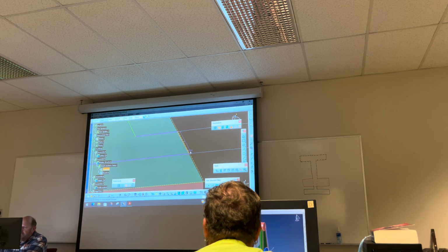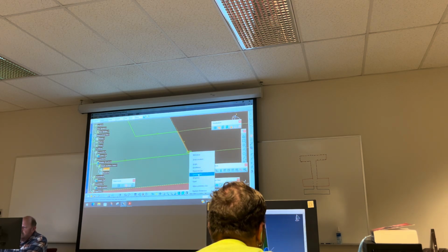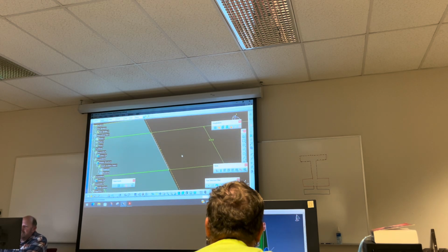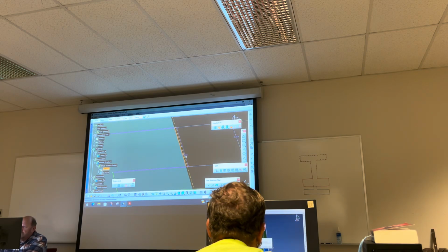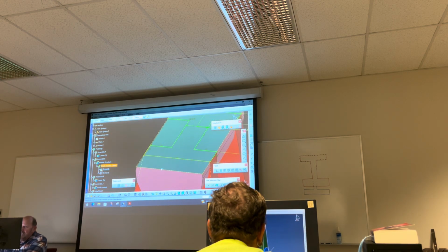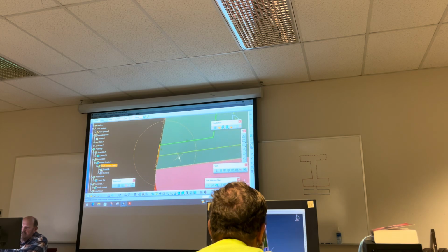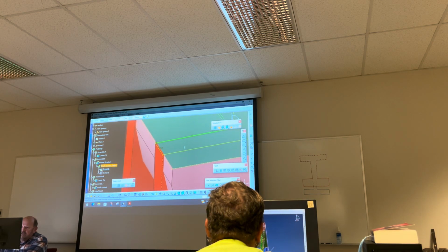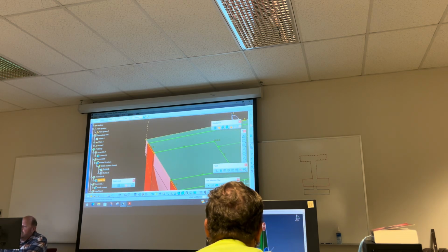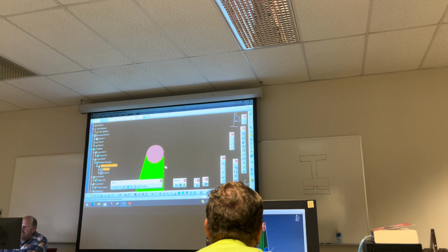So let me pick that, this, coincident. Okay, that moved, and I hope this one looks like it's disconnected. So I'll do that one as well. From here to here, coincident. Okay, that one's lined up. And over here, this one looks good. So I'm gonna exit this. Now, I'll see if this will let me fillet that edge.